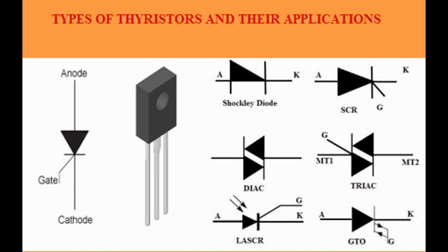Applications. Switching applications, used in circuits where precise control of turning on and off is required. Pulse circuits, employed in pulse generation and timing circuits. Counters and registers, utilized in digital circuits such as counters and shift registers. AC and DC motor controls, used for controlling the operation of motors in industrial applications. Advantages. Active turn-off capability. Unlike SCRs, SCSs can be actively turned off by a gate signal, providing better control over power switching.